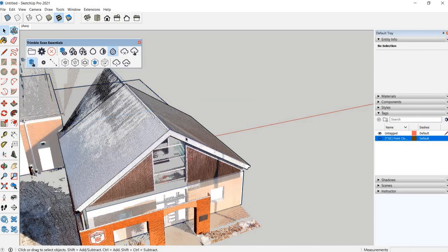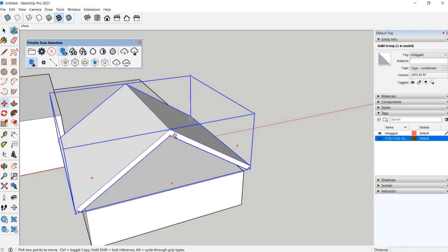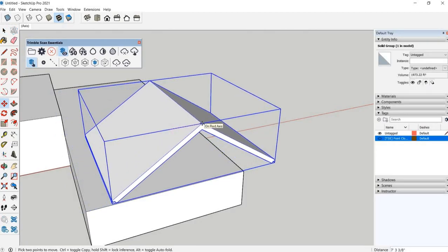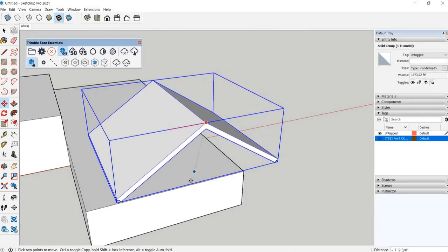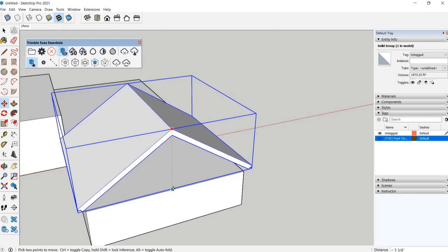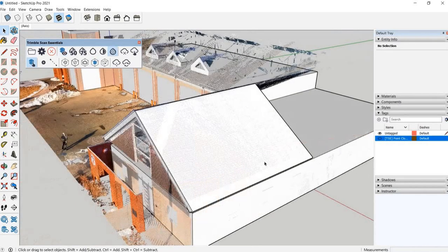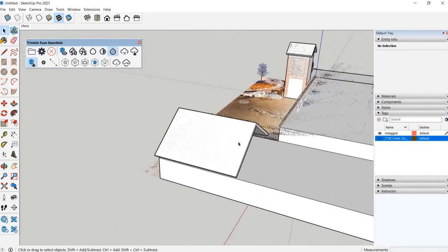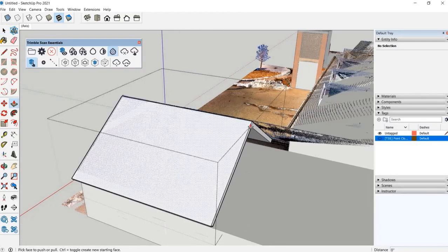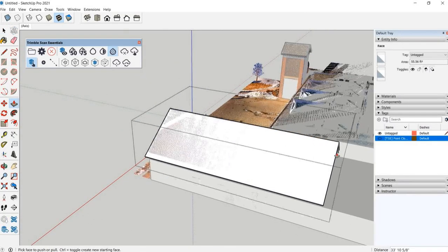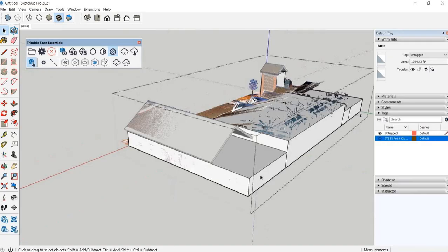Make sure our roof is grouped, and then I'll move this roof from the ridgeline endpoint, lock the red direction, and reference the midpoint below. It's kind of incredible how small this move is, and speaks to the overall accuracy of the scans. But even though this is a tiny alignment, it's so important to keep your SketchUp geometry clean and aligned.